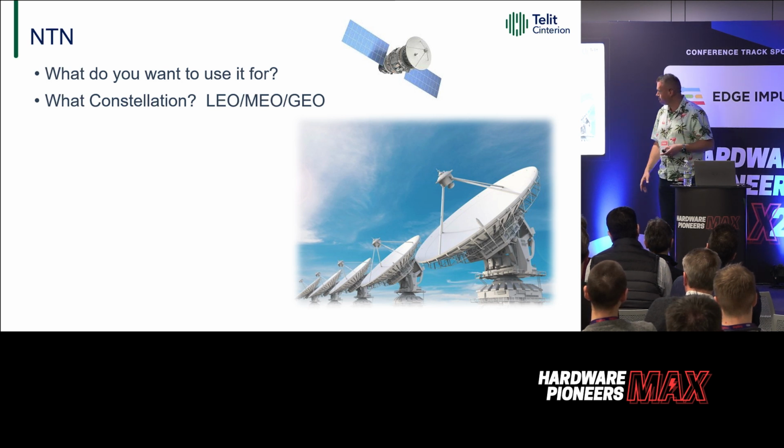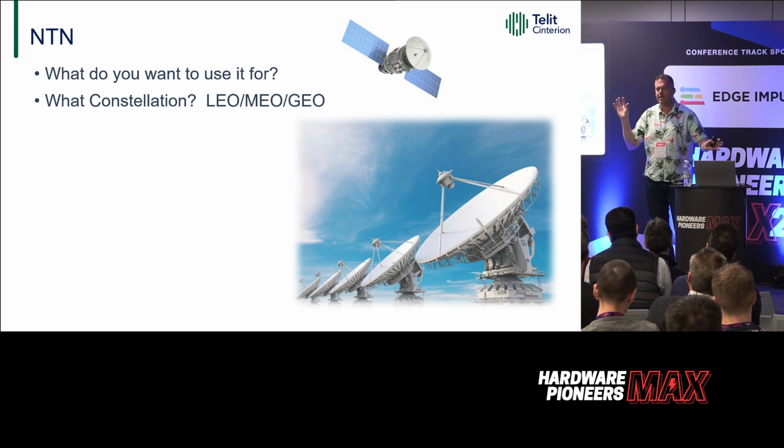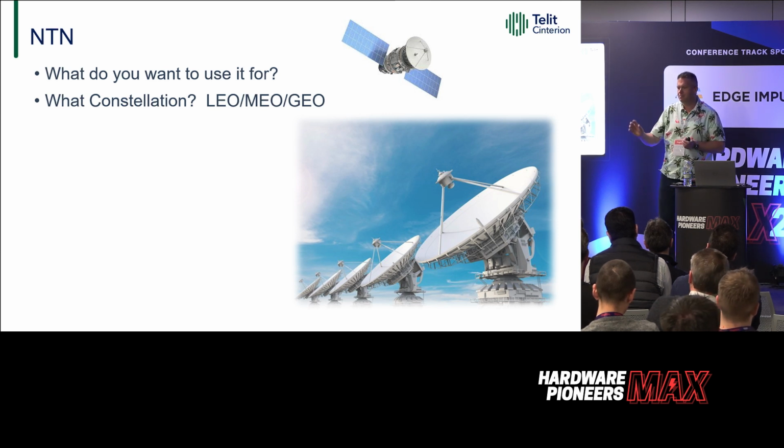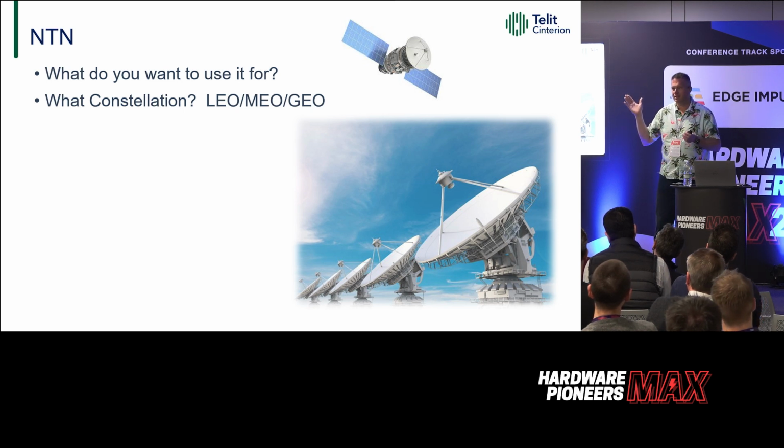I did try hard. But the LEO and the MEO, of course, these satellites are mobile, a bit like the GPS satellites, okay? Which means you're going to then have to start worrying about things like azimuth and elevation and velocity, the sort of ephemeris information that you have to worry about with GPS receivers. And then you think about your antenna, and then you think about satellite handover. And it increases complexity quite a lot. But with the LEOs and the MEOs, you can get higher bandwidth. With the GEOs, it's typically lower because they're much further, okay?